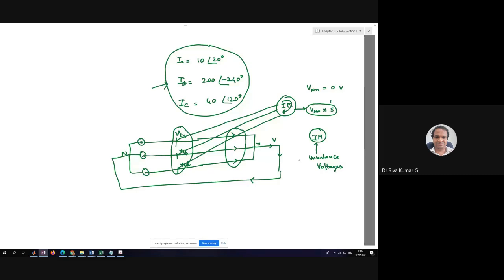I have given an example for a case of a three-phase, four-wire system. If it is a three-phase, three-wire system and you have the voltage unbalance, we'll have circulating currents in these phases. If you don't have this particular fourth wire, then we have the circulating currents. It is not usual practice to allow a circulating current between the two phases.